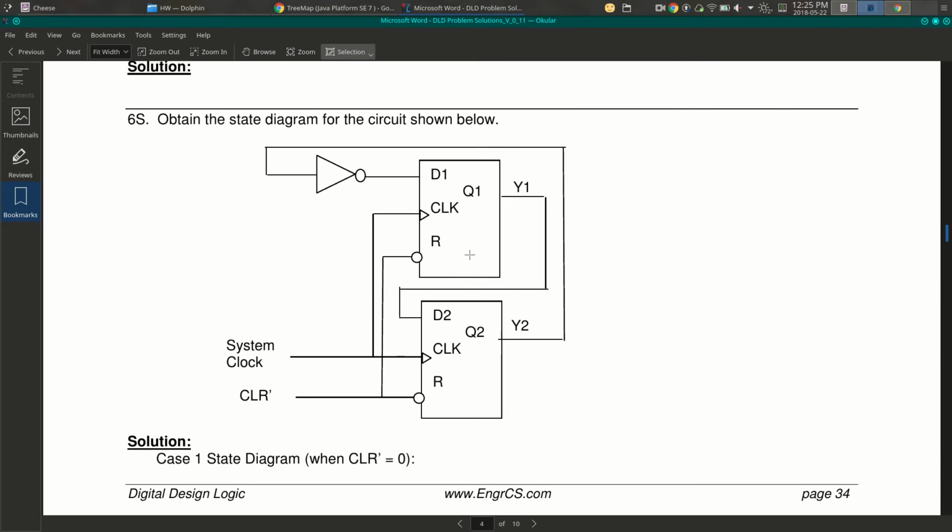So a lot of different kinds of flip-flops have this reset. Sometimes it's called clear. And if you assert that signal, then it forces the flip-flop to a 0. You also find devices with a preset input. And if you force that input, then it sets the value to a 1. And there's varieties of these. Some of them will happen as soon as you assert that signal. Some of them it will happen only if that signal is asserted and then you tick the clock.